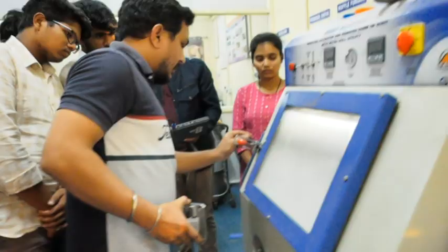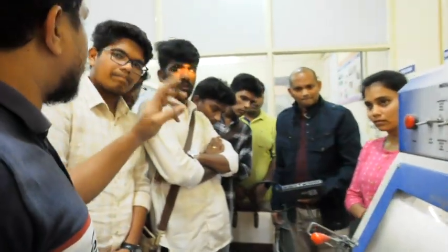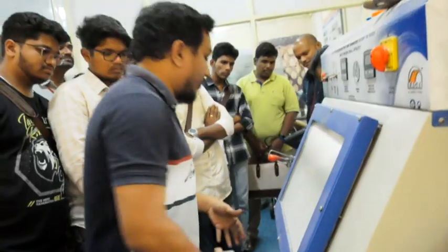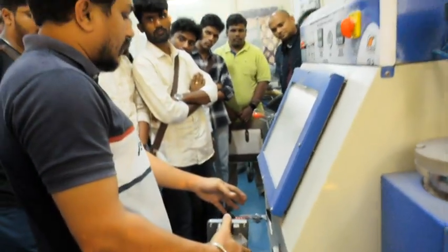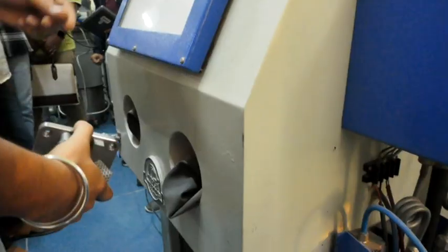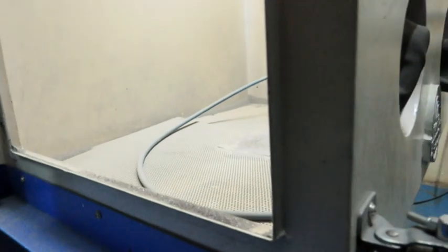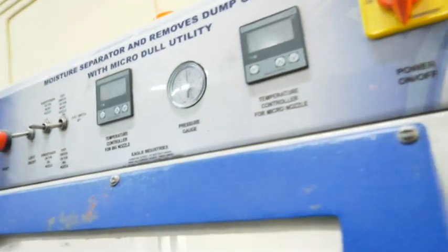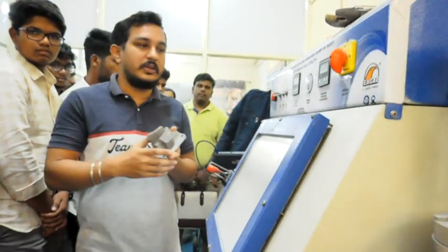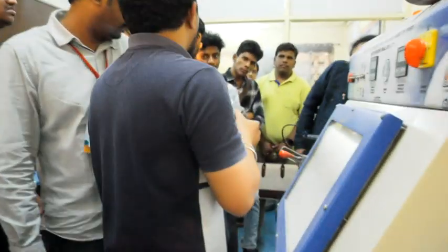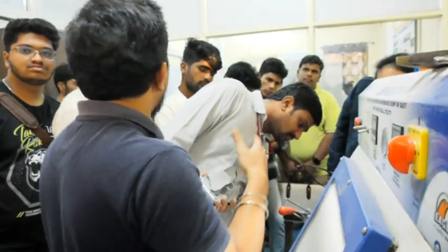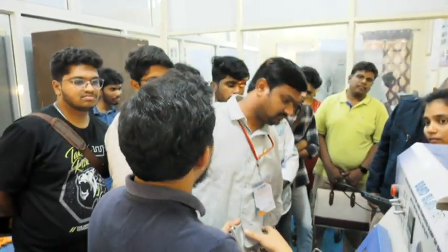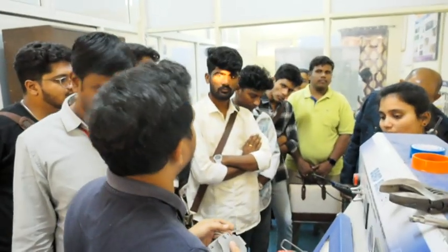It is also just like a glove box, which you have seen in LPBF. The sample will be kept inside, and you have to hold it using the gloves only. Because you can see there is some sand blast, very small particles coming with high pressure, and they hit the surface and remove the higher features. It will make the surface smoother. So there will be a large reduction in the surface roughness using this sandblasting technique. And there are also other processes, like shot peening, that will be helpful to reduce the surface roughness.